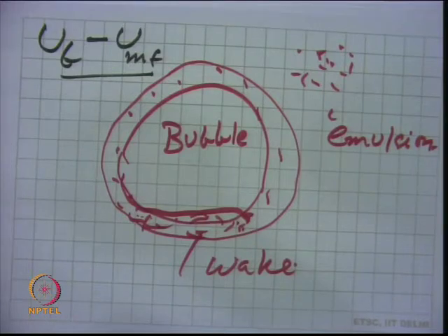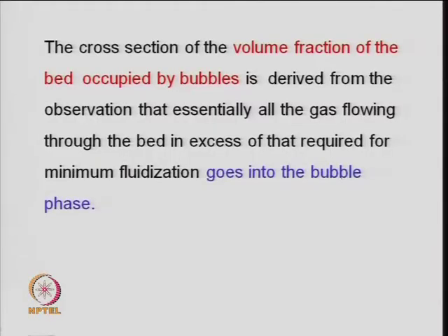That is one essence: the volumetric flow rate we calculate from the bottom of the column in terms of the superficial gas velocity is what allows the bubble to rise, and the bubble will rise only when it exceeds the minimum fluidization velocity. So, the bubble rise velocity also we have to define accordingly. I am not going into the details of that, but one should have some idea when looking at fluidized bed reactor design, and details can be covered in subsequent courses.